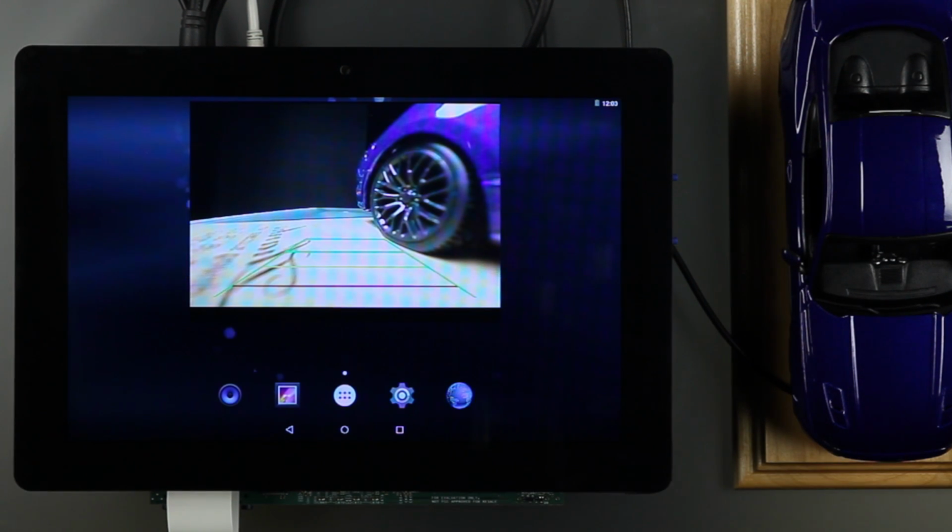The fast start of the rearview camera video is accomplished by loading a firmware image to a set of auxiliary dual ARM Cortex-M4 cores shortly after power on of the infotainment processor, and running this ARM Cortex-M4 code image before the main infotainment operating system, in this case the Android OS, starts to boot on the ARM Cortex-A15 cores.